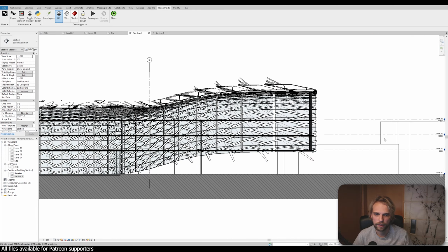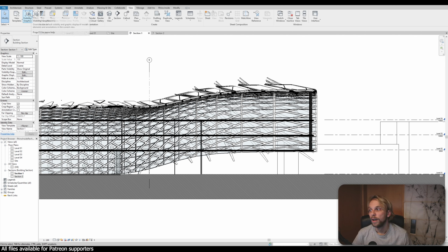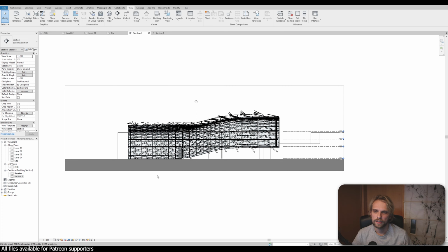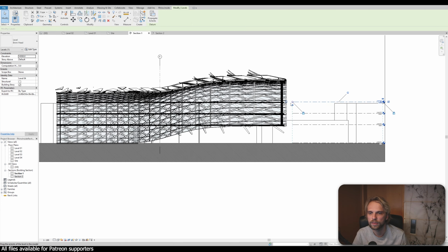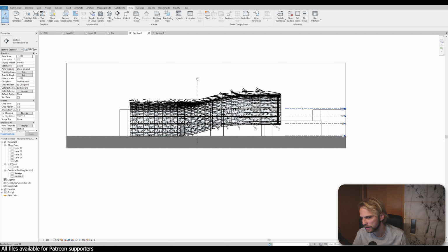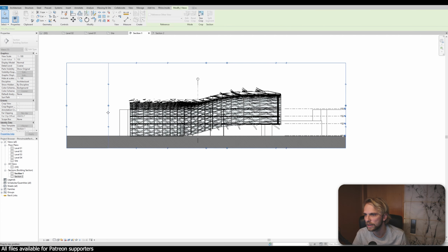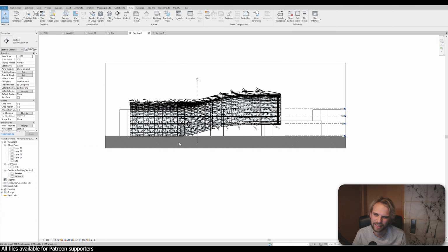That's great. And then for the generic models, which are only our surrounding landscape, let's go back in here, view, visibility and graphics, or actually let's keep them white, I guess, because they're kind of in the back this way. So I'm happy with this. This seems like a decent, an okay drawing, right? I could start unpinning and messing around with it here, but let's keep it the way it is. Also, the abrupt ends in terms of design are not that great, but you know, small steps.